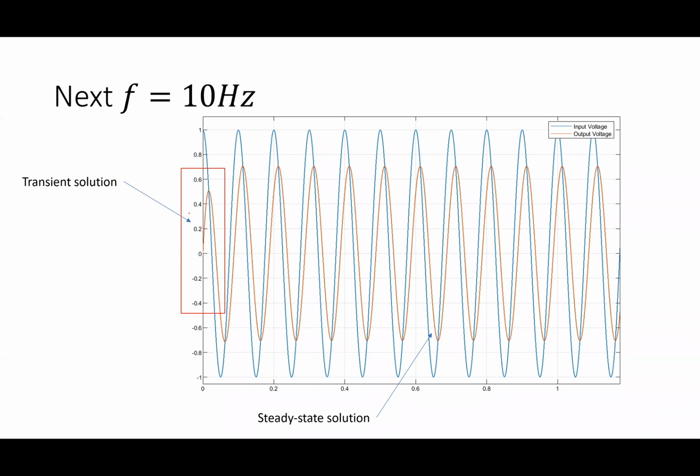What does the transient response of any differential equation look like? What type of function is always in the transient response? Exponential, right? And that exponential always does what if I wait long enough? It goes to zero, after about 5 tau. It dies out, and I'm left with essentially a sine wave. All right. And so when we go into AC circuits, we're not going to worry so much about the transients. We're going to worry more about what happens in steady state.